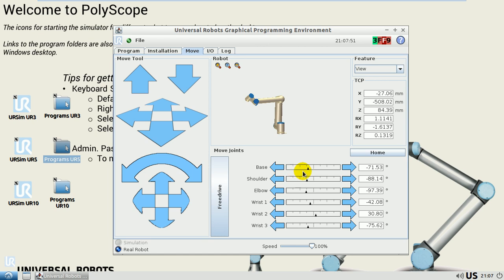In other words, if I press this button, I can move only one motor at a time. But if I press this button, multiple motors will move, based on the kinematic calculations of the robot controller. Again, multiple motors are moving. So this all is calculated by the robot controller: how much current, how many degrees of rotation to be given to each motor joint.